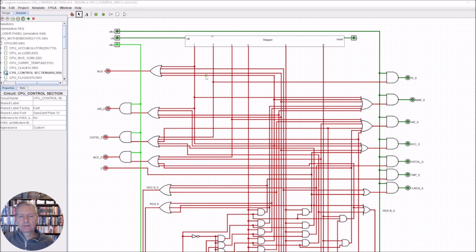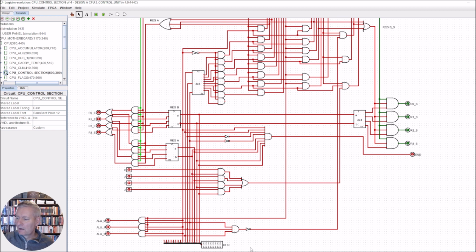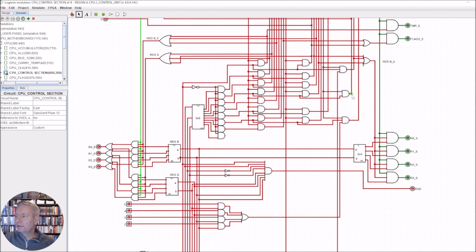How are we going to take this hardwired control unit and change it so that we can generate complex instructions and also more instructions without increasing the complexity of the actual control unit? So let's start off by having a look at the control unit. We're going to have our instructions coming in the bottom, and these instructions are decoded via this combinational logic. So the combinational logic here really is the heart of generating our instructions.